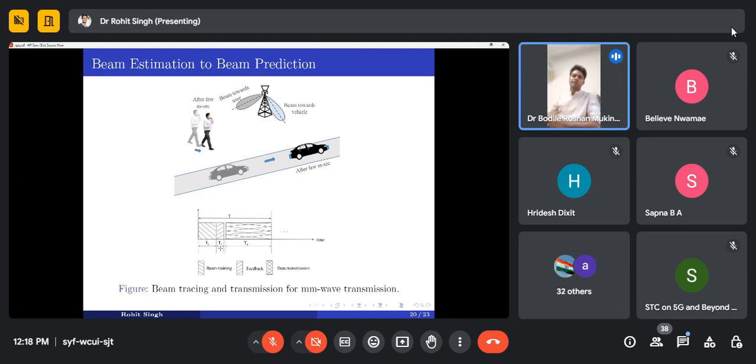for calculation and feedback only. So if this t, the coherence time window, is very small, that means the time where channel conditions are static is very small, you cannot afford to transmit TD because most of the time will be taken by TT and TF only. So in case of a fast moving user, this coherence time is very small, so you cannot afford that.